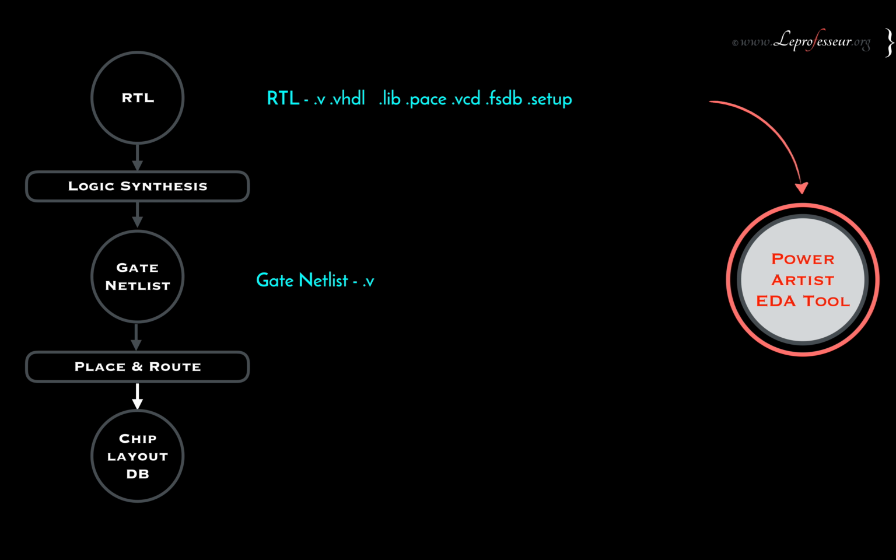Okay, when you have the gate netlist, you can give the gate netlist to the tool, and when you have a post-routed netlist, you can give that along with the SPEF file.